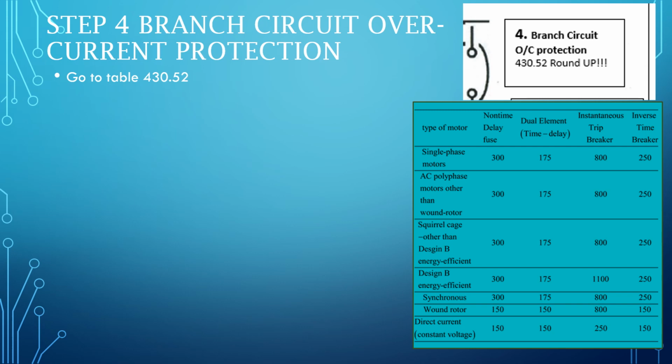But the overcurrent device that's closer to the motor is going to protect the wire. It's going to protect the system from something that's close to the same size as the motor. That was set at 125 to 140% of that motor's potential overcurrent, that's what's going to trip if we get a small overload.